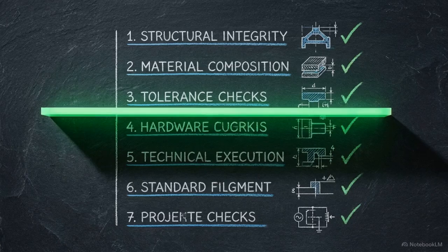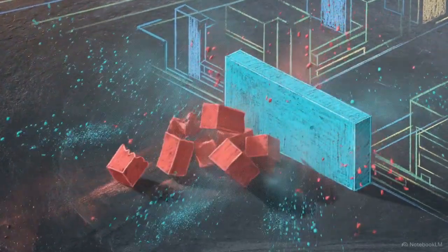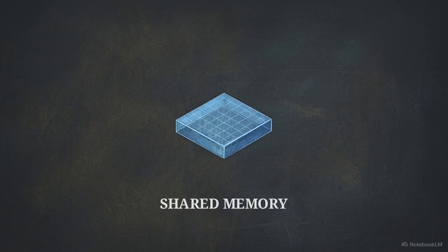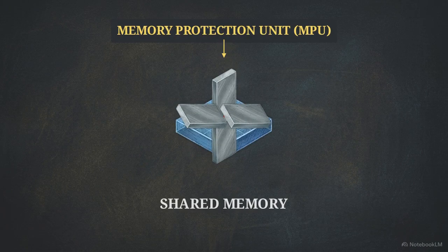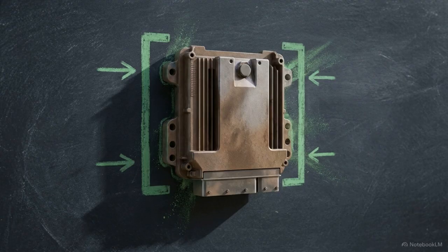Engineers use a rigid checklist of 7 coupling factors to hunt down vulnerabilities, thoroughly evaluating shared resources, communication paths, and identical component types. In practice, analysts inject digital errors into a shared memory block to see if the corruption spreads. If it does, they implement memory protection units to quarantine the bad data behind a digital barrier. By moving secondary faults into the DFA process, engineers shift the burden of environmental chaos off of a fragile mathematical equation and onto a robust system of physical and architectural defenses.